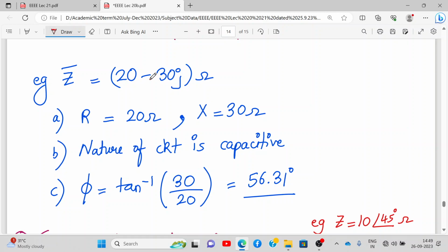No, we don't take the negative sign into the formula. We have seen that in the analysis so far; we have not taken a negative sign. Only the angle is negative. Impedance and resistance are never negative. It's always positive. Even if it feels like it's negative, what happens is current and voltage are leading or lagging behind each other. That is the only thing happening. But resistances are purely positive only.